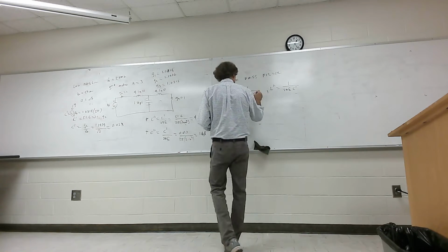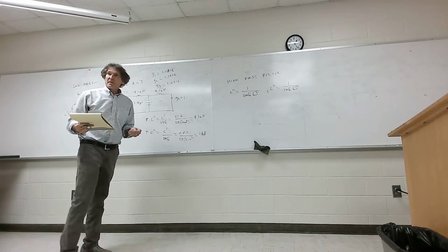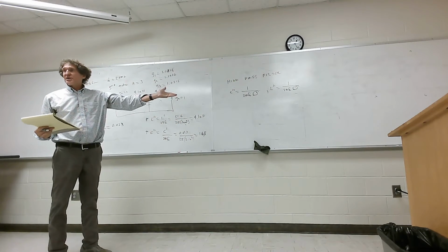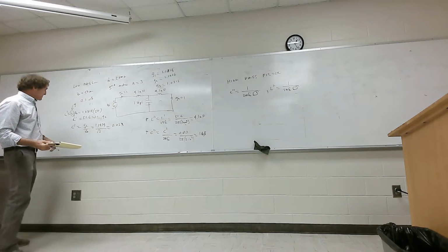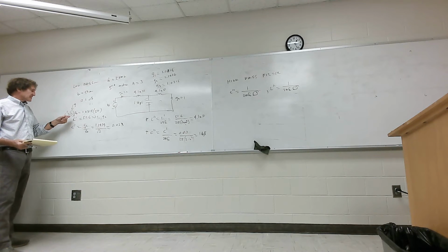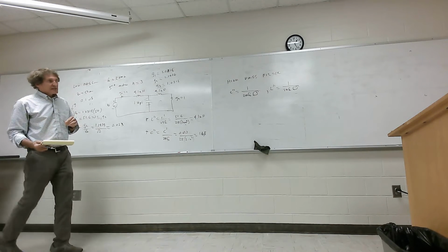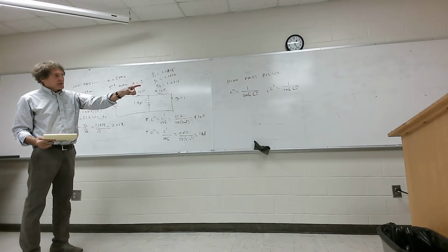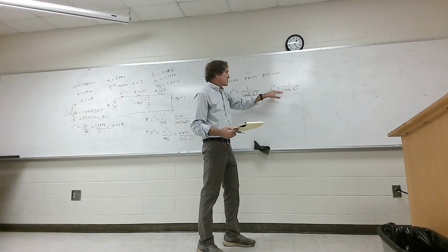Now, this value and this value were from the intermediate steps for the low pass filter. Do you all remember? Those values are given by taking the values, if it's a series L, and multiplying by Z naught, or if it's a C, taking G divided by Z naught. But this is in the book, it's spelled out. So you're going to get these values right here and do this transform.